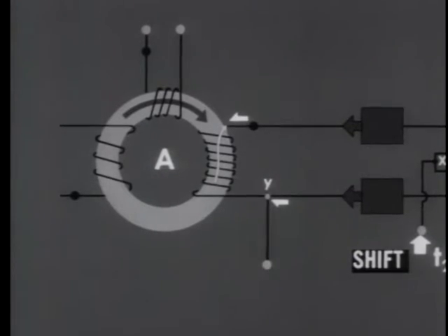As a matter of practice, however, a small coil is inserted into the lower connection to provide a counter EMF there that will balance the counter EMF in the output winding. Therefore, the upper branch pulse meets no more impedance than the lower branch does. The impedances are equal, and so the branches are equal.